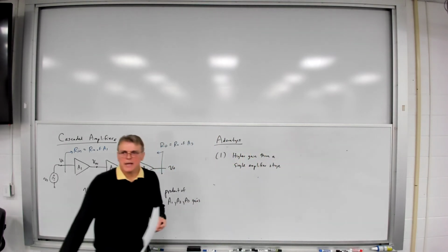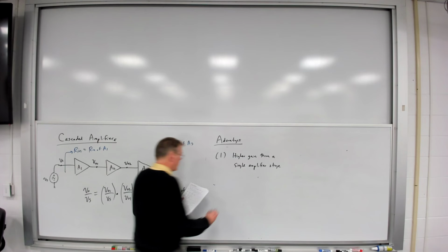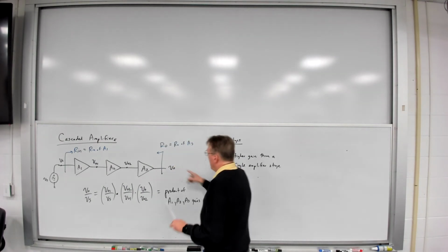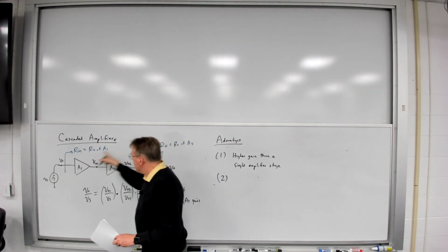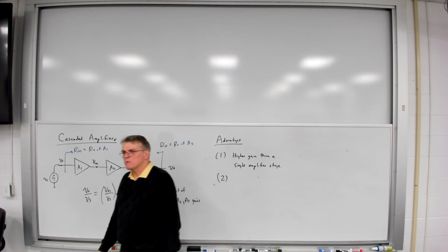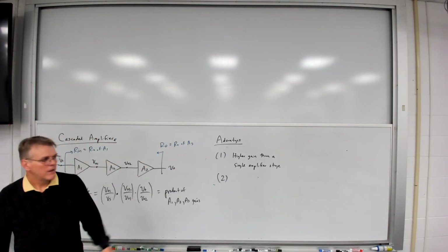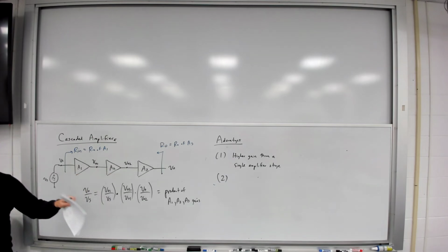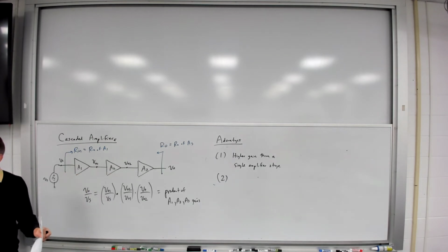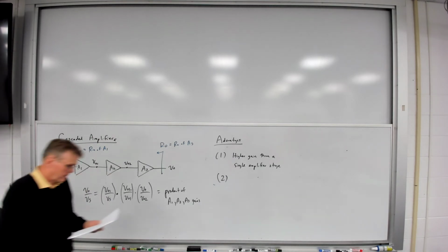So I get much higher gain, but the other thing I get is this. I can mix and match my input and output resistances depending upon the types of amplifiers I use. So I can get different input-output resistance combinations than I could with a single stage.